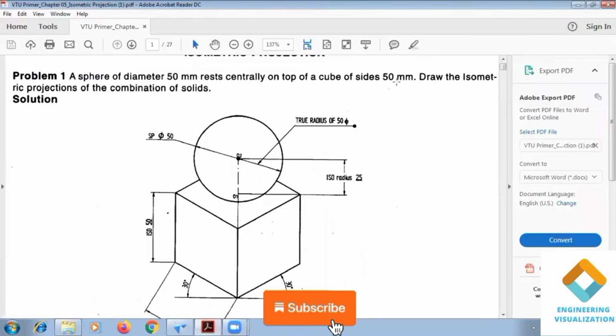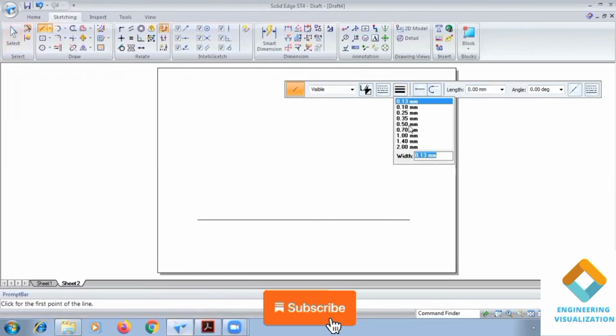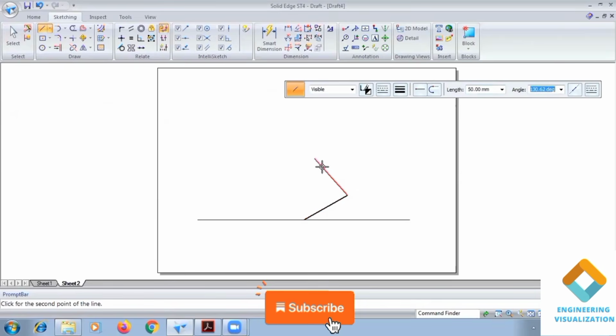So this cube has sides of 50 mm. 50 mm means we need to consider a 50 mm box. So here please consider the angles. From this reference end, length will be 50, angle is 30 degree. Again length is 50, angle is 150 degree. Then again length is 50, angle is 210 degree. So like this we need to construct the box.